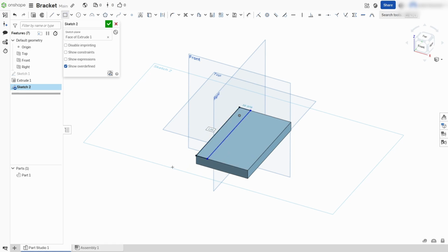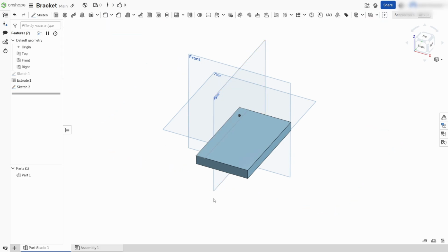We're just going to drop it, and then resize it with our dimensioning. So dimension this edge to this edge, and that's 13 millimeters. That's good enough. Originally this here is 13, so we want to extrude this up 90.